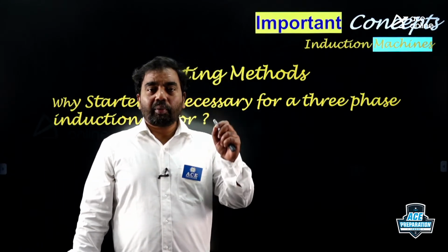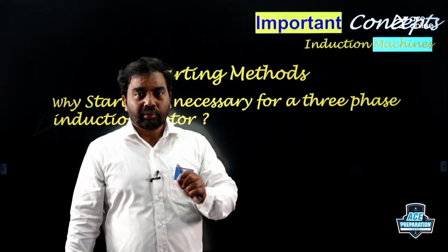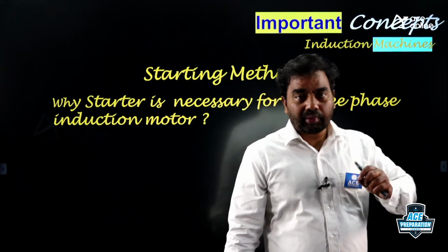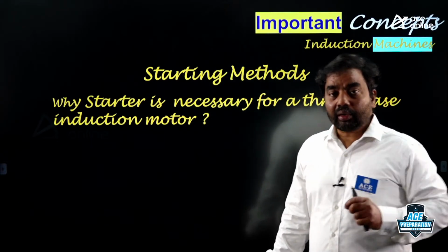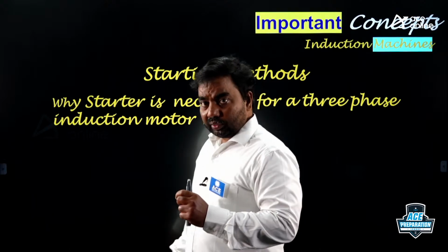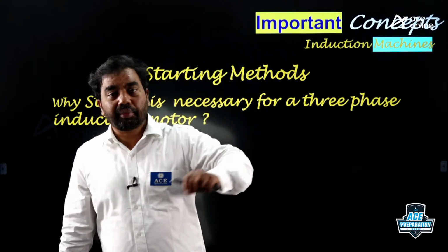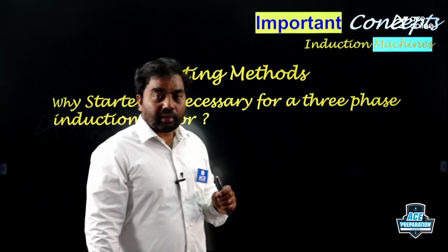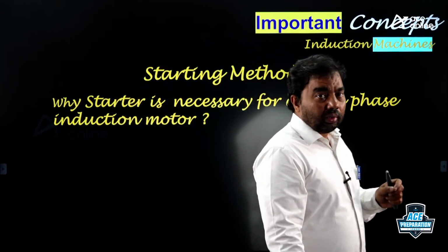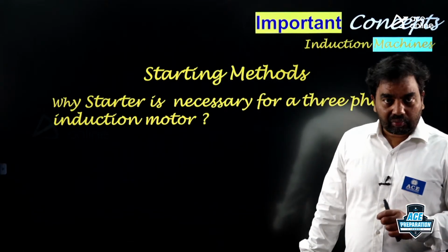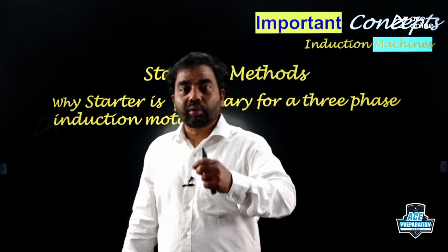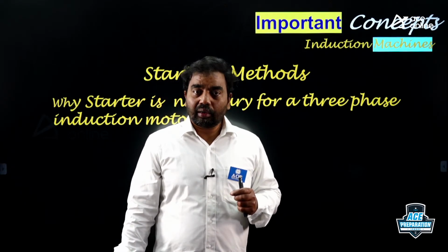How? Let me just brief it out. Whenever we give a three-phase supply to the three-phase stator windings, which are spaced at an angle of 120 degrees, then we have a rotating field. This rotating field cuts the stationary rotor conductors and an EMF is induced. The induced EMFs in the rotor conductors will establish a current.